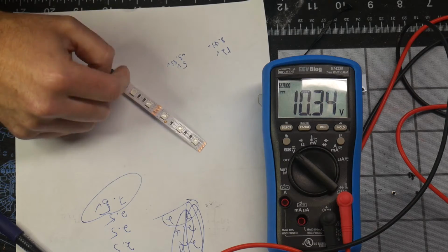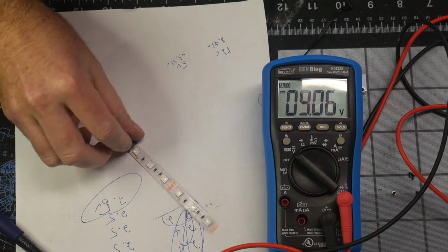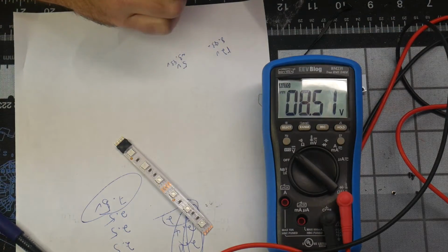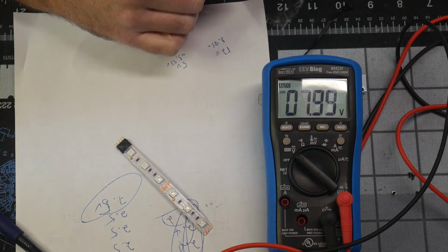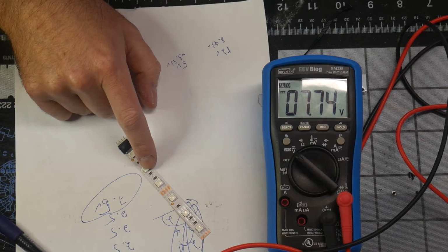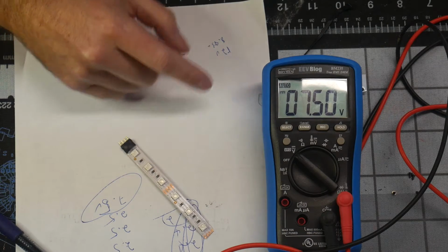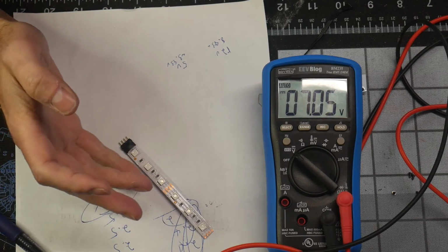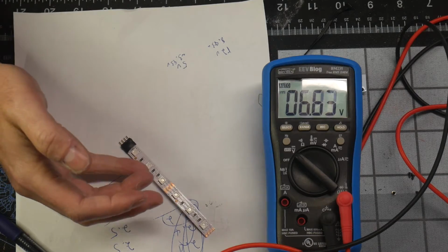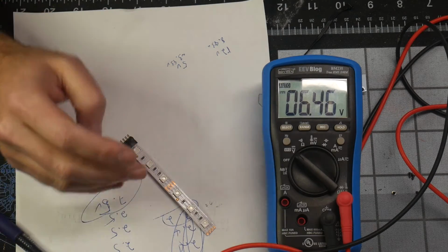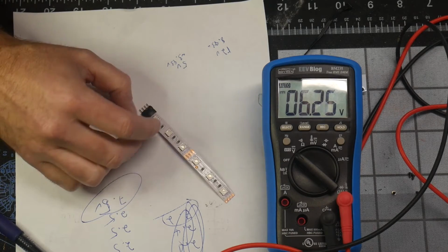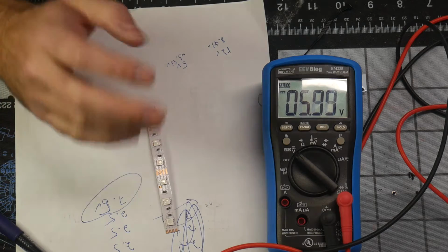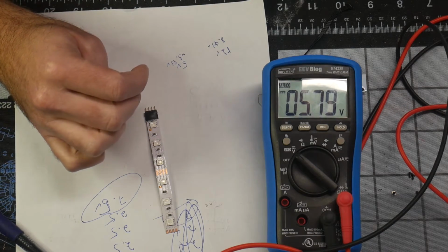You can get the voltage drop from all the LEDs right here. You can check out how many resistors there are per LED diode, and from there you can just get the voltage, see what these are. There's calculators online where you can just say how many LEDs I have and what the supply voltage is, and it'll tell you the voltage drop for all the LEDs, and that will tell you what resistance values you need. So there's a couple tools out there, and I'll probably put a link in the description to show you guys how to do that. But this is just kind of a brief overview.